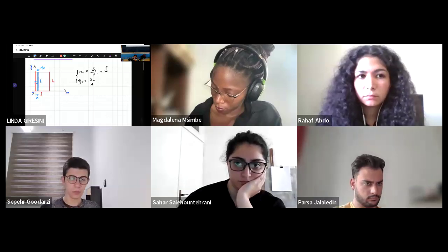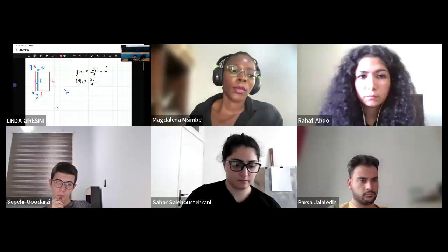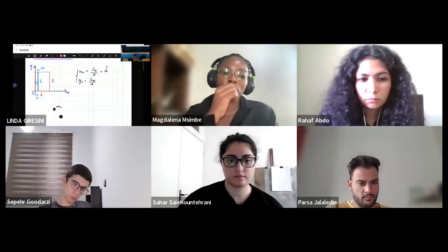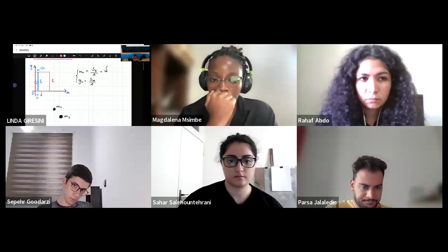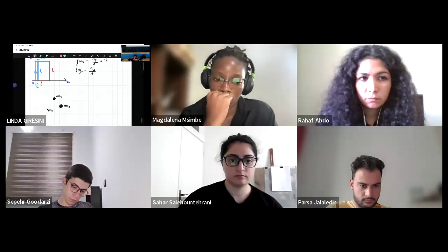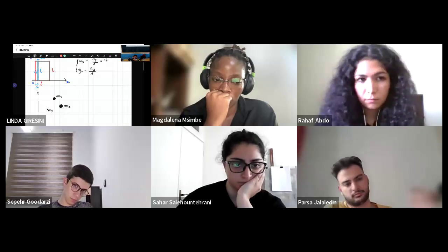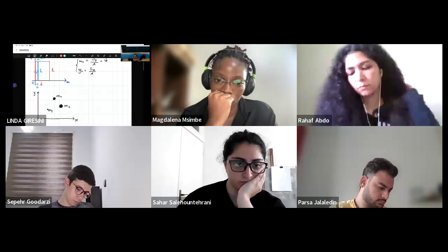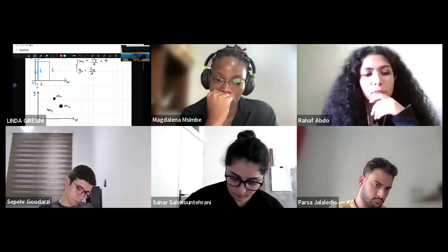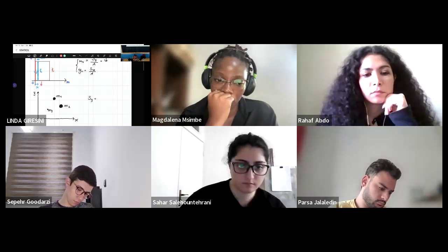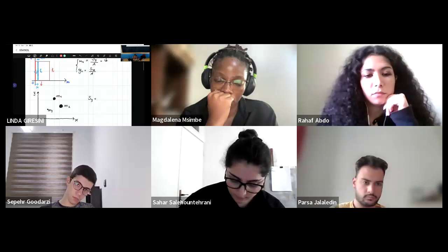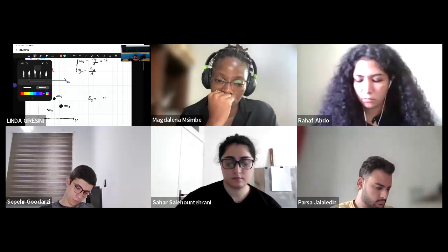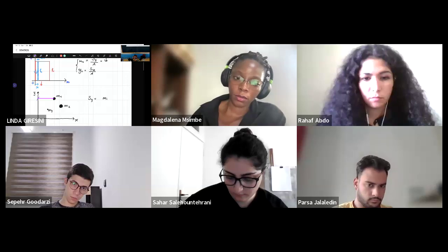Just to be clearer, if you have masses, for example, mass M1, M2, M3 concentrated in 3 points, and you have coordinate axes, X and Y, the static moment of these masses with respect to Y is the product of each mass Mi times the distance of each mass from the y-axis.